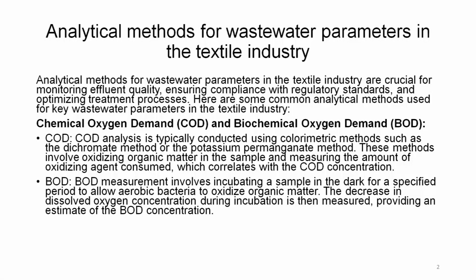Here are some common analytical methods used for key wastewater parameters in the textile industry, that is chemical oxygen demand, COD, and biochemical oxygen demand, that is BOD. COD analysis is typically conducted using colorimetric methods such as the dichromate method or potassium permanganate method.